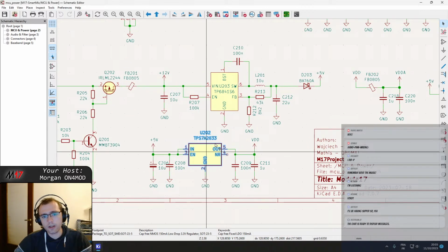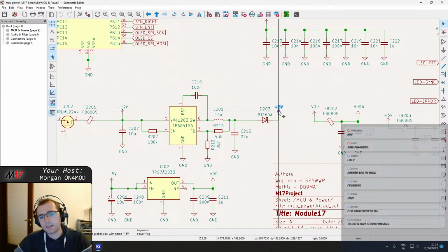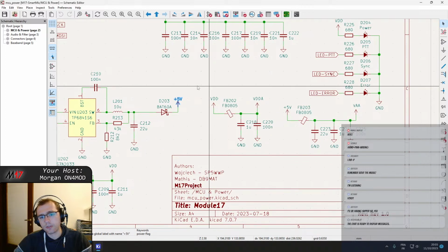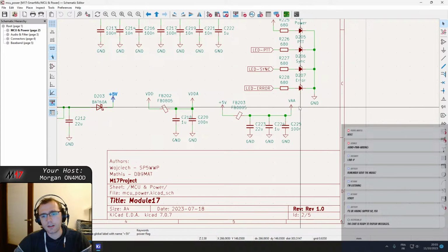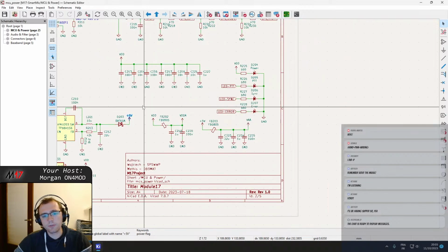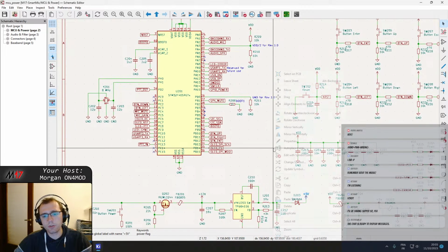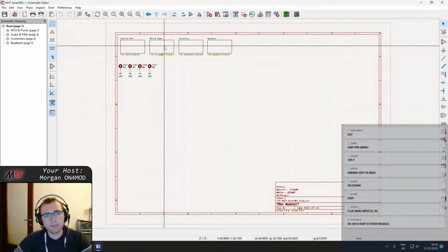So this one is much quieter, but this one has some switching noise. But the problem is that this 5 volt goes through a ferrite bead and then some decoupling capacitors to become the VAA. So VAA and plus 5V are both 5 volts, but VAA is slightly filtered.